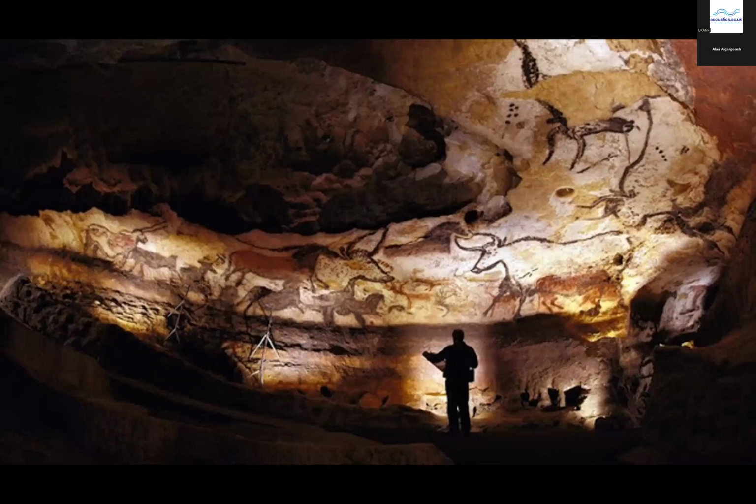So how is analyzing and designing complex acoustic environments related to well-being? Resonance. I wanted to understand resonance, analyze it, and recreate it. Room modes have been considered as sound defects, but are they always negative? Room modes are the resonances that amplify sound frequencies and suppress others, and therefore they change the tonal characteristics of the sound. So it has been reported that in some historic and worship spaces, the resulting resonance can provoke an emotional response that enhances the listener's experience.